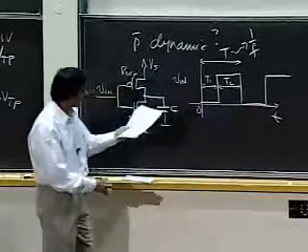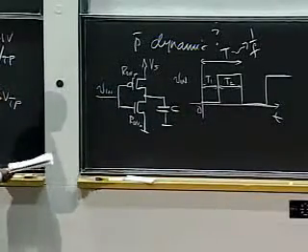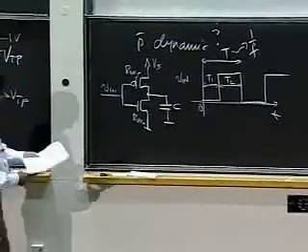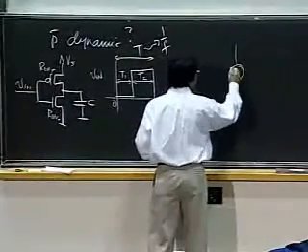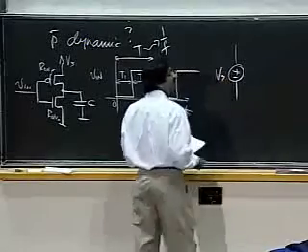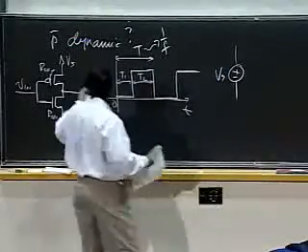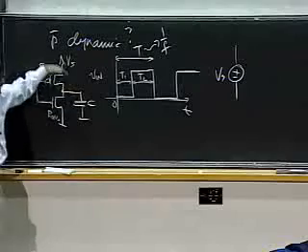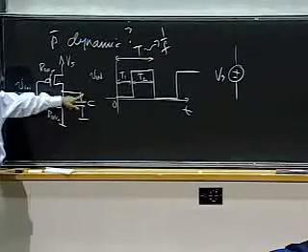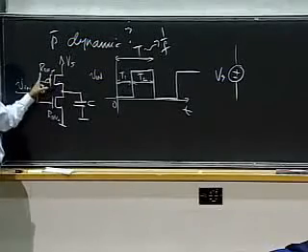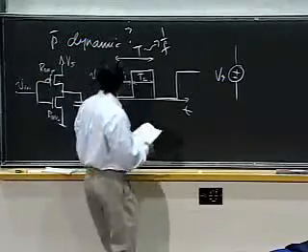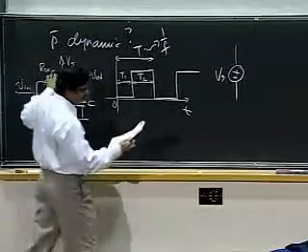So in this situation, if I assume T1 and T2 are much larger than the respective time constants, I can go ahead and draw my equivalent circuit. So here's Vs. For charging up, let's say this one is going to a 1, or to a high. So I have Vs going through a resistor R on P to a capacitor, and this thing is a switch.